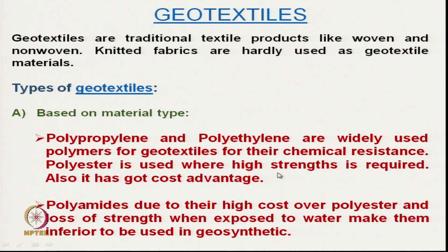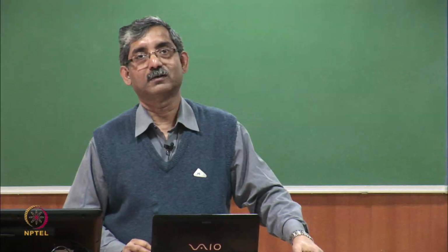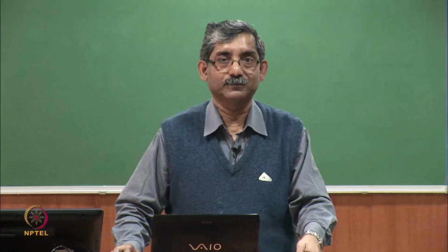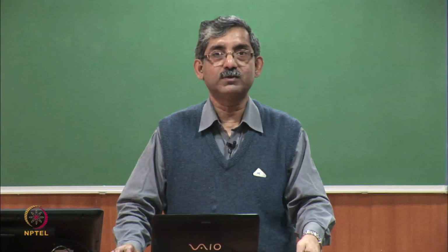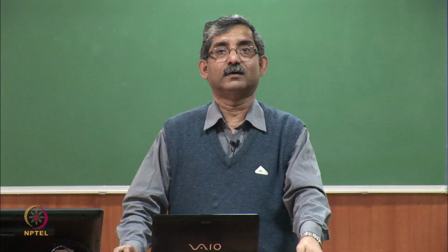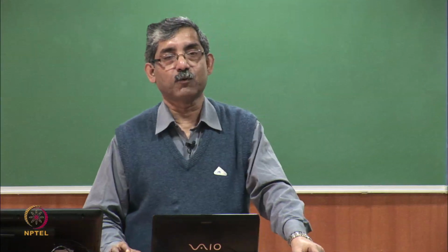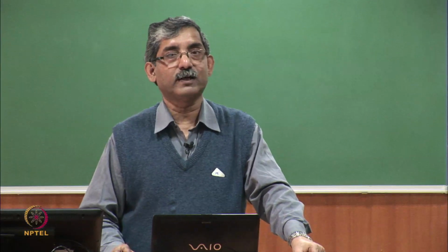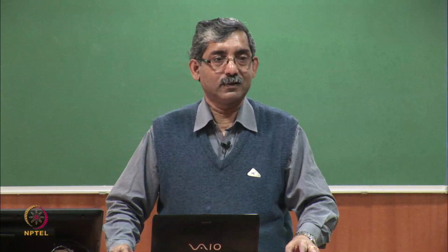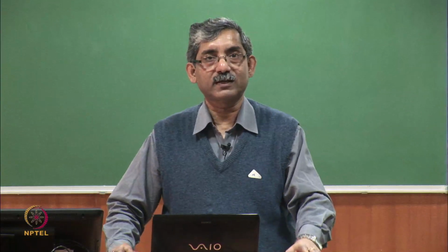because in geotextile, when it is always in contact with the soil, rocks, definitely there will be interference with the water. That is why polyamides are hardly used, but for some applications where abrasion resistance is important, because polyamide has very high abrasion resistance, it can be used. PVC fibers are rarely used. It can also be classified based on the manufacturing technique.